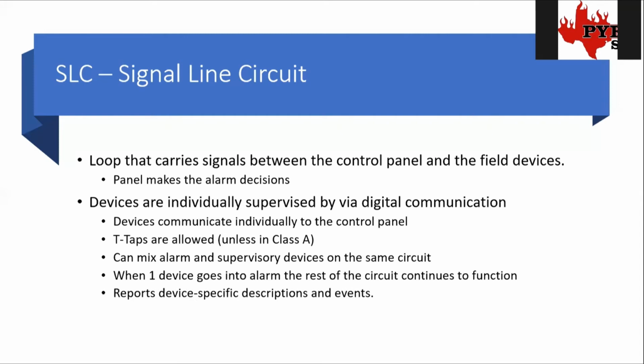So that's what SLC is. And in the last slide, I talked about as far as troubleshooting goes for the IDC circuits, you do it the exact same way you would troubleshoot a NAC circuit. Signaling, the SLC is a little bit different. We're not supervising it with an end-of-line resistor because all the devices are talking.